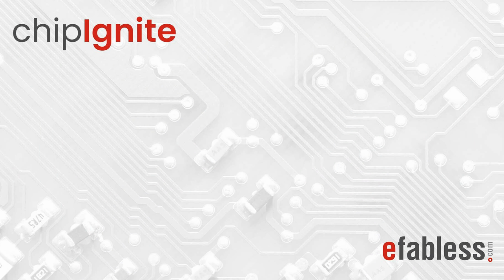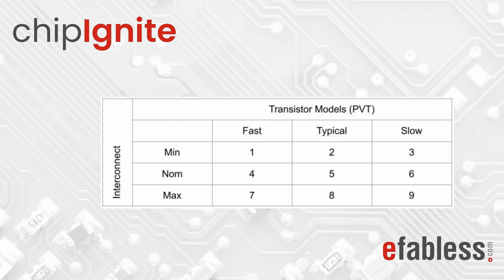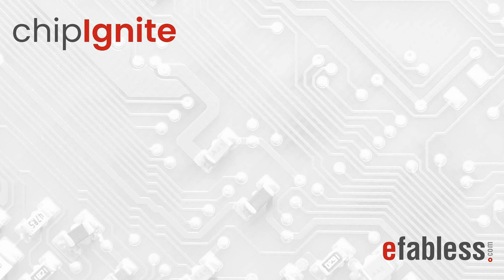The sign-off STA is performed on 9 timing corners, which are combinations of 3 PVT corners, fast, slow, typical, and 3 interconnect corners, min, max, and nominal. The star-RCX_STA star.rpt reports are for the typical nominal corner, and the star-MCA directories include the min, max, and nominal corner combinations respectively.